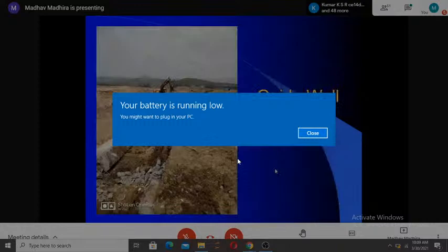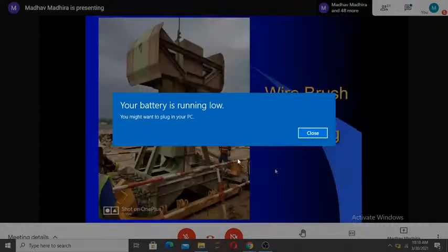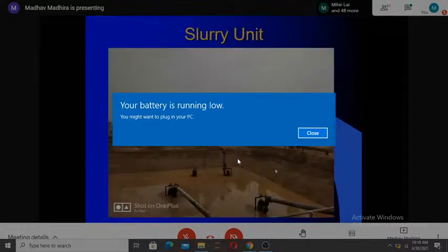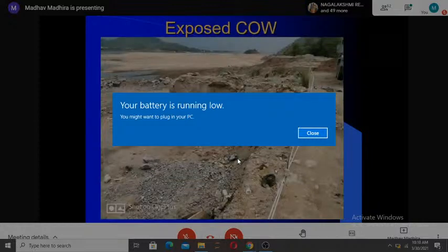You have a guide wall through which you introduce the diaphragm wall. This is a cutter, which is about 5 meters wide, 1 meter thick. You can see the wire cutter and the cleaning at the bottom. This is a unit to make an opening and support the excavation before you put the reinforcement and put the cement too. And this is the exposed cutoff wall. You can see it's 1.5, 2 meters wide, and it's the best ensured so that there's no seepage below.